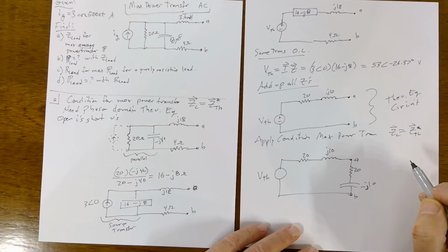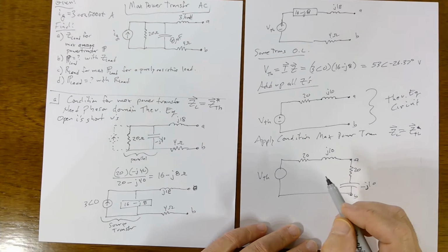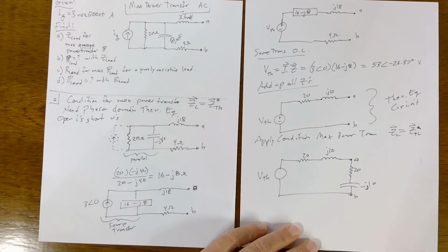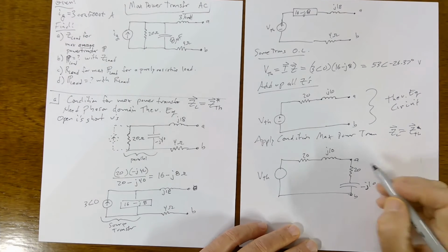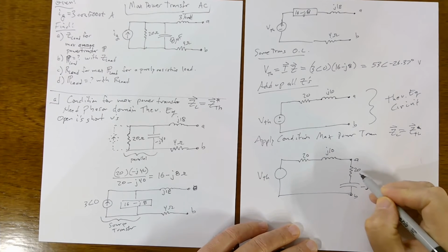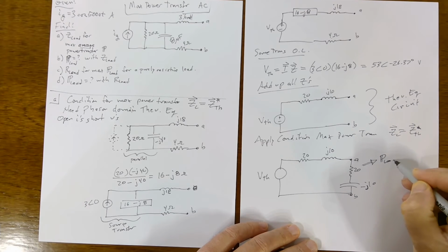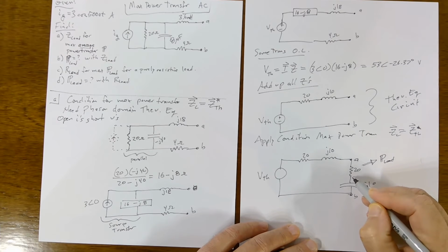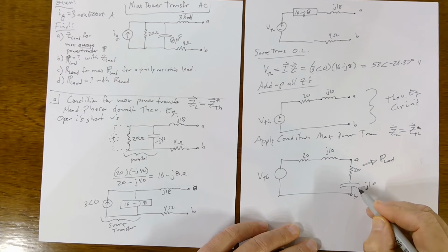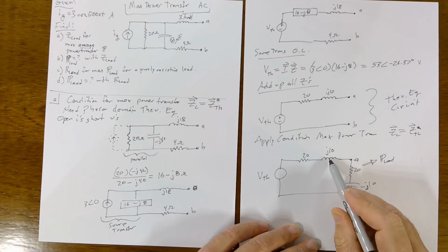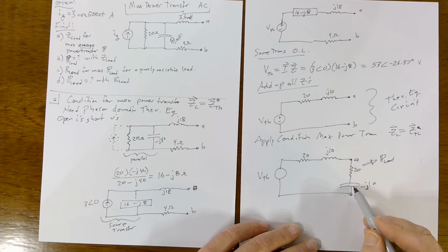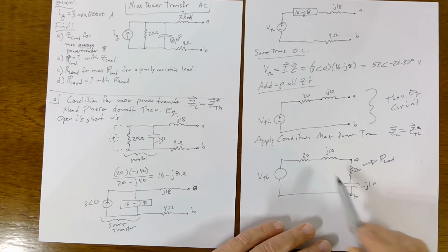Okay, so that's the trick. So we can calculate power, the real power, which, by the way, all the real power is going to come off in here, right? The P of the load is due to the resistance only, right? The inductor and the cap cancel, but if they didn't, there would be some Q in here.